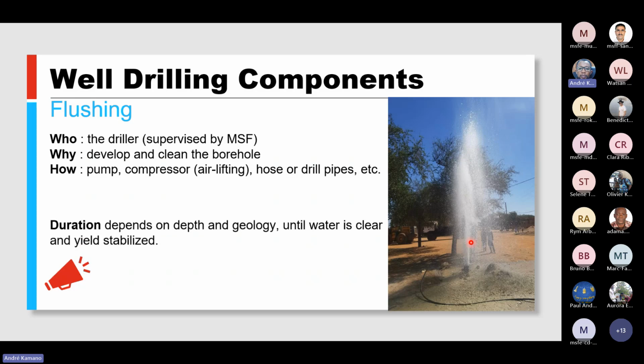The flushing also has to have a duration, which will depend on the depth and also the geology. What will help us determine that we can stop the flushing is when we have clear water, and when we know that the gel is stabilized.